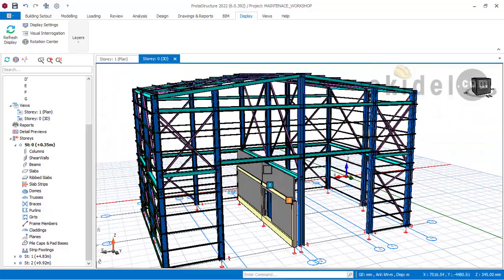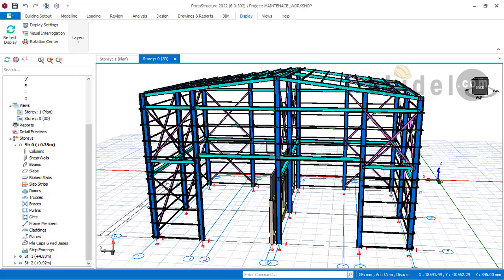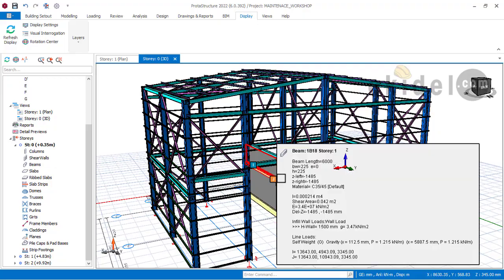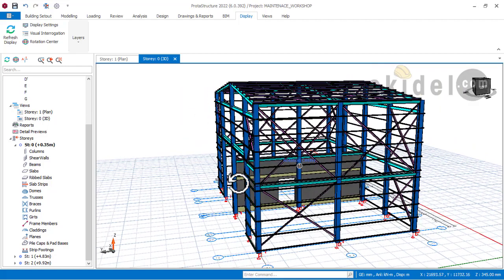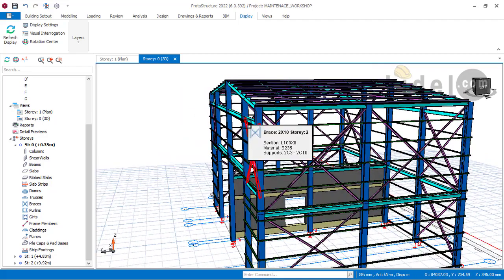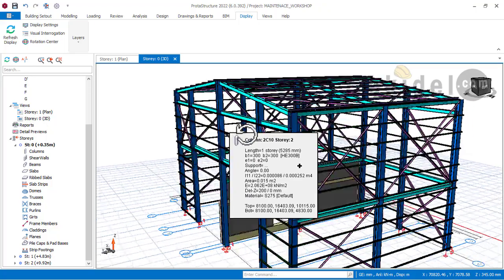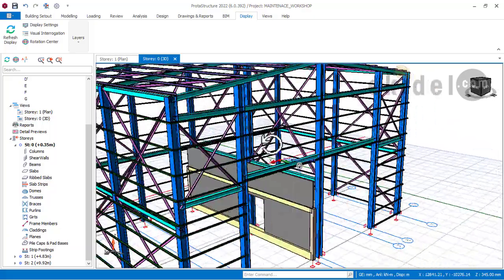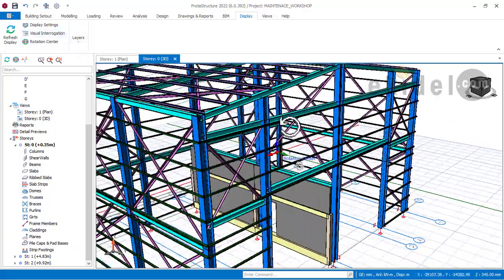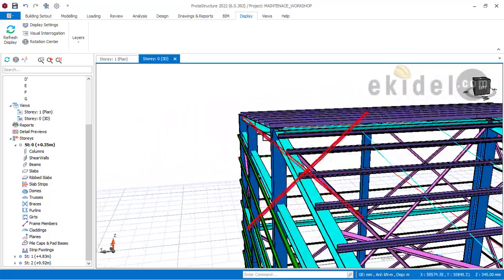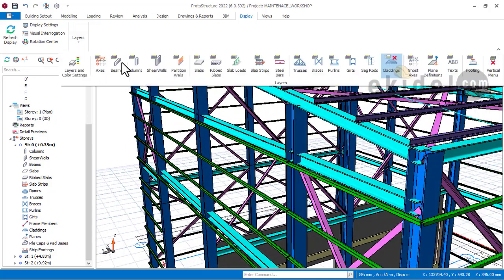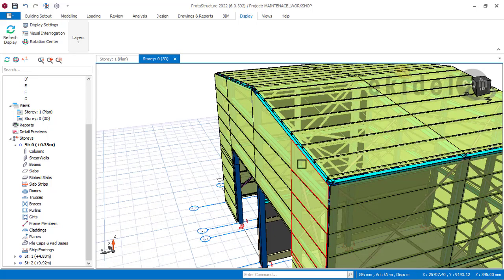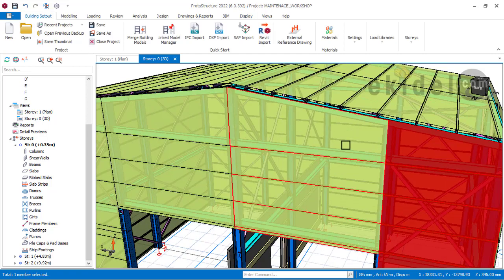Basically, this video is to show you how to create your cladding when you have different levels. Maybe you know before how to create normal cladding, but when you're designing a steel workshop building, warehouse building, and other complex steel buildings, you might have a sloping member. If I turn on my cladding now, you will see that the claddings in this area have sloping members.